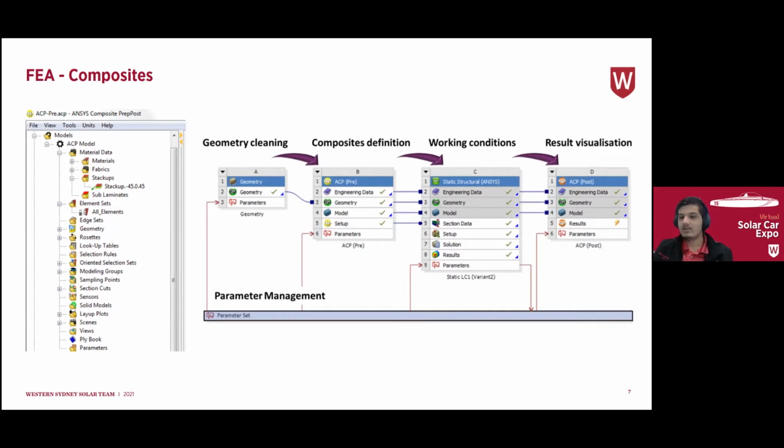The ACP method involves the design starting as surfaces and not as solids as before. Onto the various faces of these surface bodies, you can specify the layup schedule of your composite that you have in mind. We can define the type of composite, the number of layers, the angles of each layer, any core material, as well as any glue films, etc. using ACP. It also allows you to specify any relief cuts, which are often areas of concern and can be quite harmful if not designed appropriately.